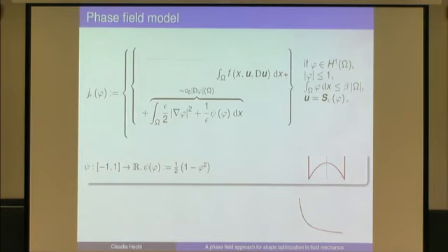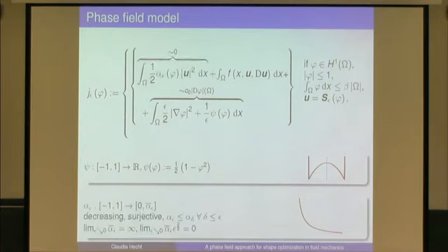Now before, we stated also for the velocity to vanish if no fluid is present, but now we somehow smeared out the interface, so we do not know what it means if fluid is present or not, so we have this diffuse interface setting. So instead of requiring U to vanish in certain parts, we add a penalization term to the objective functional. So we add here alpha epsilon of phi U squared, and alpha epsilon looks like that. So at -1 it has a very high value, alpha epsilon bar, and at 1 it's 0.